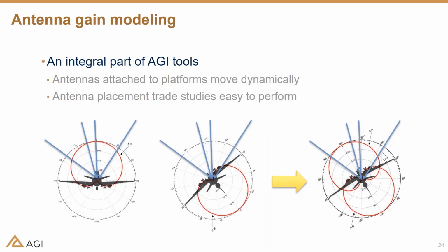Okay, so from signal jamming, we'll go back to the antenna gain modeling problem that I talked about. Again, you've got the antenna gain on the aircraft that's constant, an omni pattern. But as that aircraft rotates, again, you can see how you're going to lose signal gain. One thing you might want to do is add an antenna on the bottom of the aircraft with a similar antenna gain pattern. Now you can see that you're going to get gain while you're upside down as well from those signals. So that might help solve your problem.